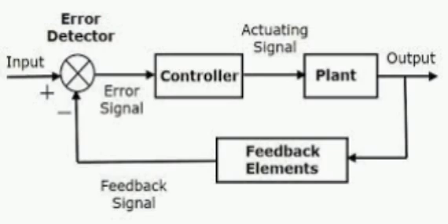Sensitivity of the overall transfer function M(s) with respect to the feedback path transfer function H(s): S_H^M equals G(s)H(s) by 1 plus G(s)H(s). A closed loop system is less sensitive to parameter variation, hence the closed loop system is better.